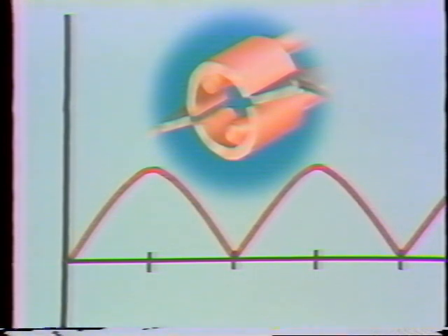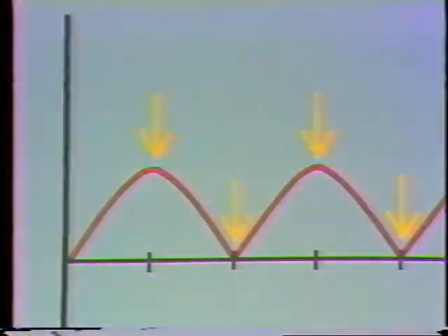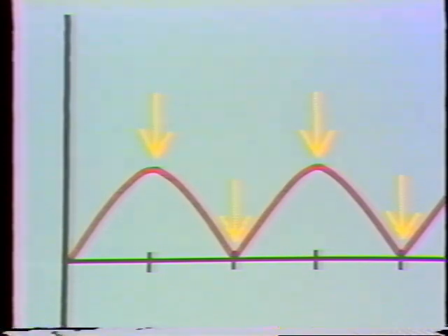It's a good thing that there's no voltage induced, because at this point, the brushes are shorting the ends of the loop. If the voltage weren't zero, there'd be an awful lot of current flowing through the loop, enough to seriously damage the generator. But on the other hand, the relationship between the commutator and the brushes means that the DC voltage output reaches its peak and falls to zero twice during each full rotation of the loop. This variation in the output voltage is called ripple, and it makes DC voltage unsuitable for many applications. Ripple also lowers the effective value of the output voltage to about 50% of its peak value.